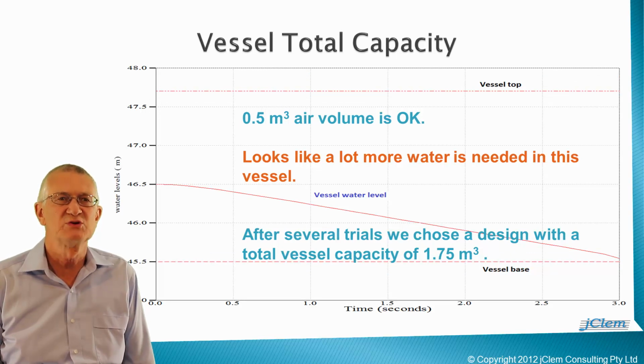This graph shows that the initial trial size is too small. It will empty 3 seconds after pump power failure. Obviously, I need to increase the size of the pressure vessel while keeping the same initial air volume. There is little value in demonstrating the trials used to increase the physical size of the vessel in this example.